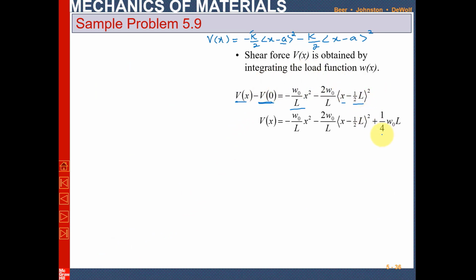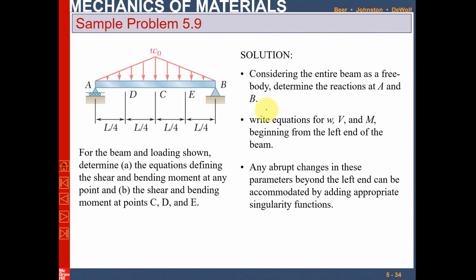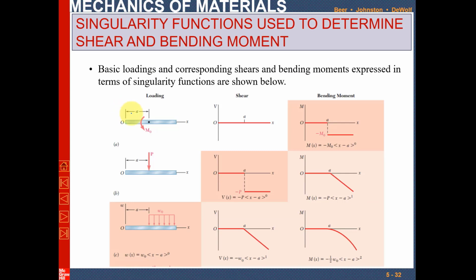So when it goes to the right side, this term will be for the linearly varying load, and this will be a concentrated load. Again, if you do not want to write V naught, you can write the equation for this, and at the last you can also use the shear force equation for the concentrated load. So you can see, let me show you it as well. You can see load for the concentrated is minus P into x minus a to the power 0.